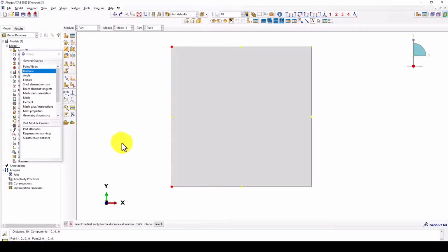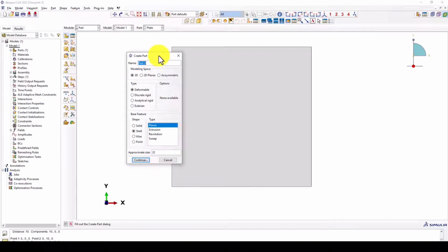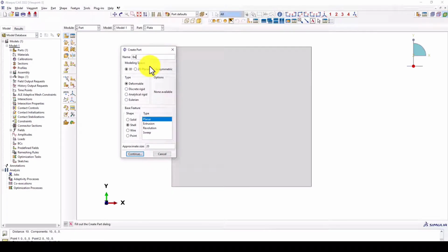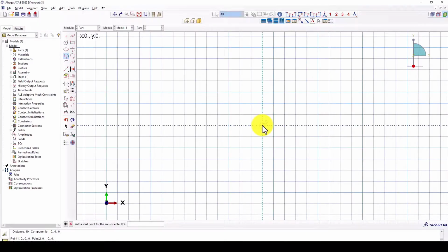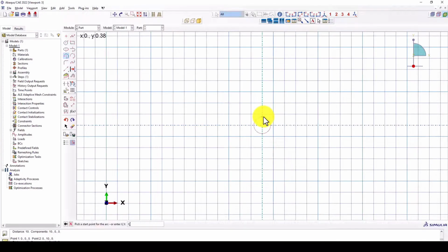The important point is that the term low velocity does not simply mean that the velocity is numerically small. That's a general misconception that a user has. The physical response depends on several factors, which are mass, velocity, geometry, material properties, structural stiffness, contact characteristics, and the duration of the impact. As we know, the kinetic energy of the impacting object is particularly important. So if we double the velocity, the kinetic energy increases by a factor of 4, as we know that K is equal to half m v squared. This is one of the reasons why increasing the impact velocity can dramatically change the response.